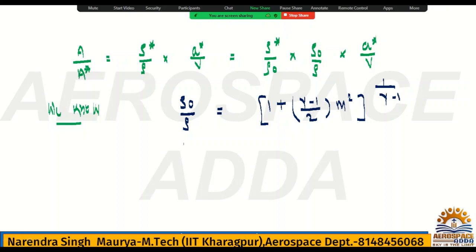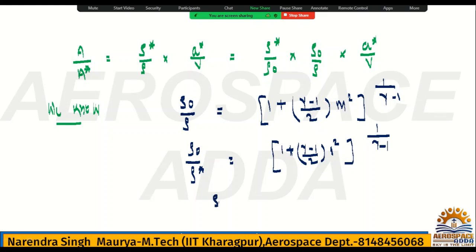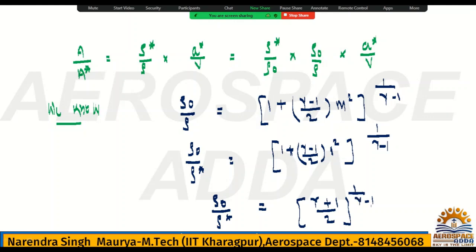At the same time, if I write rho naught by rho star, then this M will be 1, so it is 1 plus gamma minus 1 by 2 into 1 square, to the whole power 1 upon gamma minus 1. What is rho naught by rho star then? If you solve this, 1 plus gamma minus 1 by 2 is gamma plus 1 divided by 2, to the whole power 1 upon gamma minus 1. Yes or no?